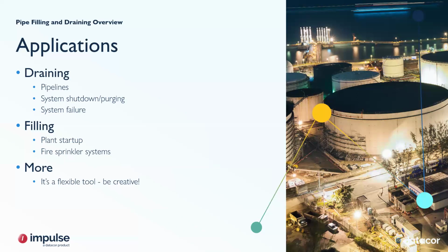The interface doesn't necessarily need to be a direct physical contact. It could be used to model a piston between pneumatic and hydraulic components if you want to treat the piston as frictionless. So feel free to get creative with it once you have a good grasp on the modeling assumptions. And if you're not sure whether this modeling approach is a good fit for your system or for your product, you can always reach out to one of our sales engineers. It's also possible that one of our cavitation models or partially filled pipe options will make more sense for certain analyses. So we're here to help if you're not sure what approach you should take.